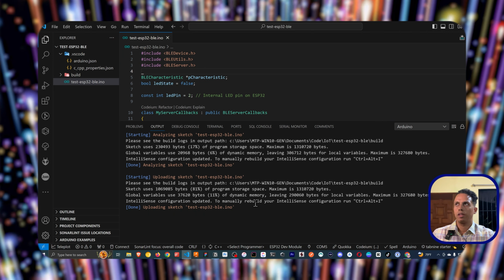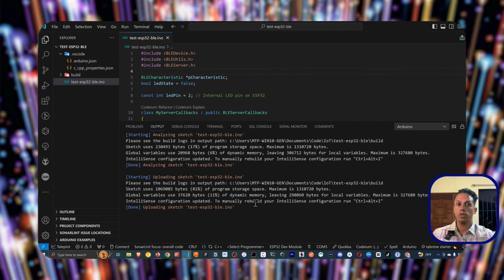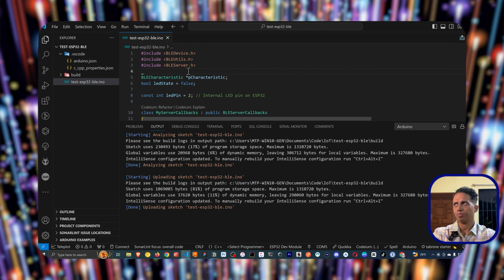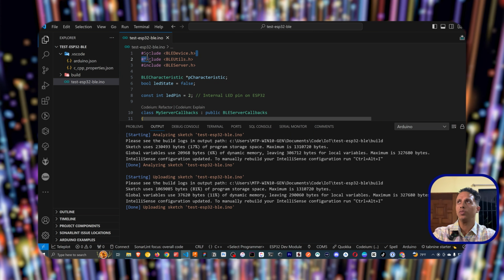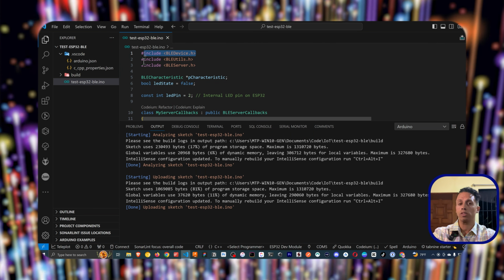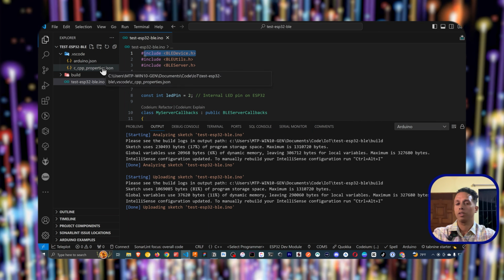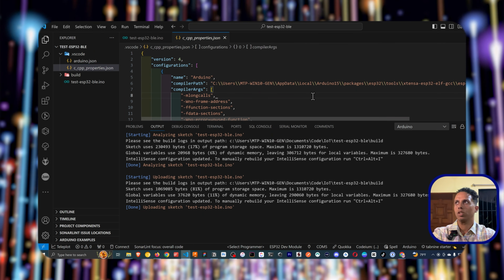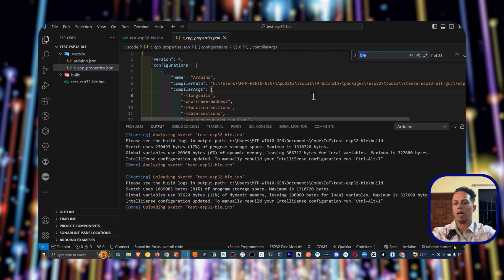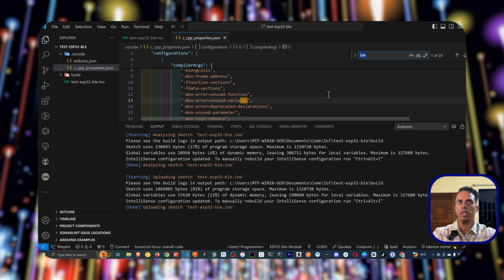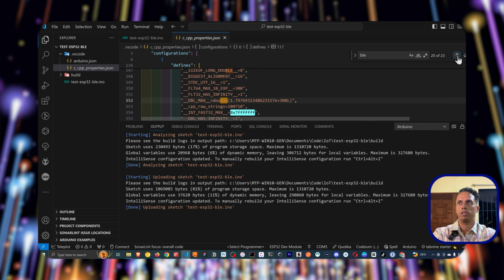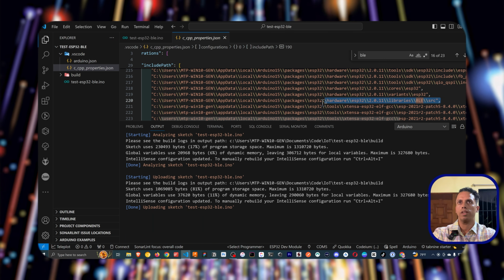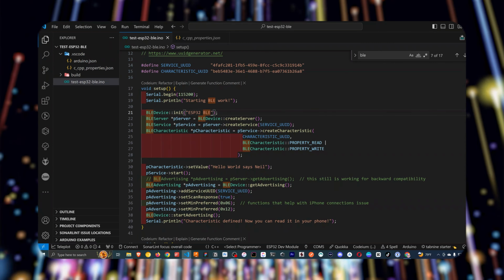Alright. Now after you've uploaded the code, you will see that it has been successfully uploaded, and at the same time, it has removed the library, since it already found the library which we're using under the ESP32 projects. If we actually look inside of the config of the libraries that we're using, if I look for the BLE, you will see that it is right here. It is under the config.